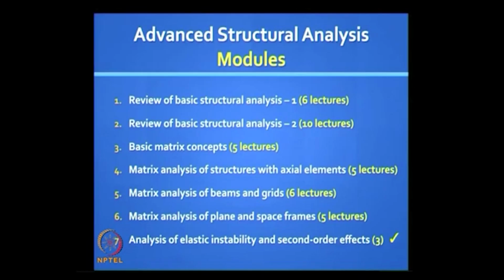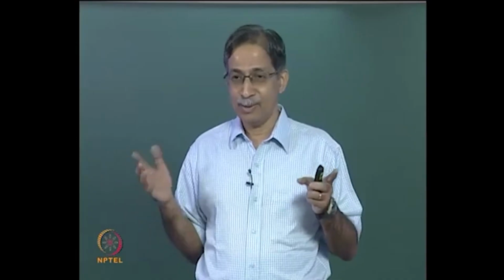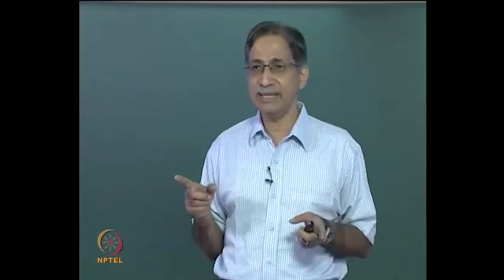Then in the second review we spent a lot of time on indeterminate structures. We first looked at statically indeterminate structures, and we looked at complex problems including elastic supports and grids and so on. Then we did displacement methods, and that is a new thing, a topic which I believe is not very well learnt in many universities. We did not study them independently, we looked at them together. We did an introduction to displacement methods, then we looked at slope deflection method and moment distribution method, and the real thing we learnt is how we can dramatically bring down the degree of kinematic indeterminacy by having a feel for the structural response, taking advantage of releases, guided fixed supports and hinge supports. We also looked at how you can deal with frames which had symmetry subject to lateral loading, how you can simplify the analysis. We also looked at approximate methods of lateral load analysis. So we did all that.